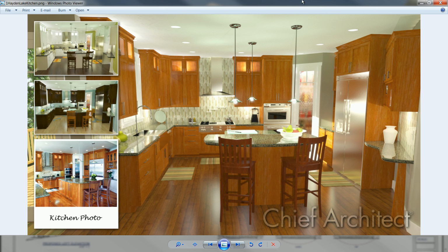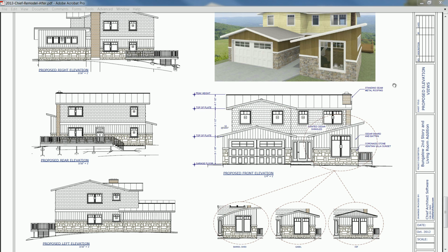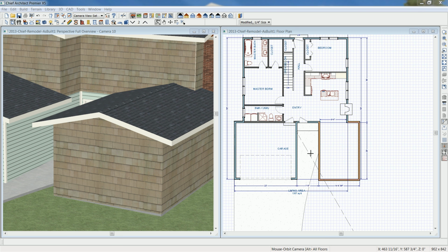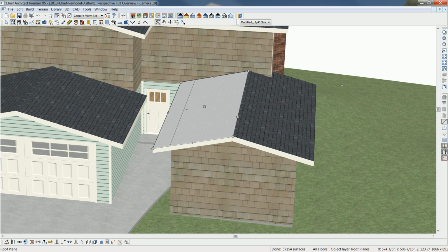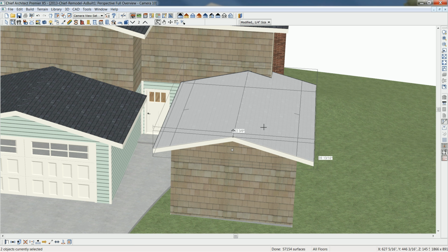So in the case of the roof style here, let's go ahead and explore. We've already done the hip style. We've already done the gable style. Let's look at a barrel, and then eventually we'll move forward with the shed roof. So I'm going to create our barrel roof. Let's go ahead and maximize the 3D view for the time being. I'm just going to simply highlight the two roof planes and shift click. I've got both of them.